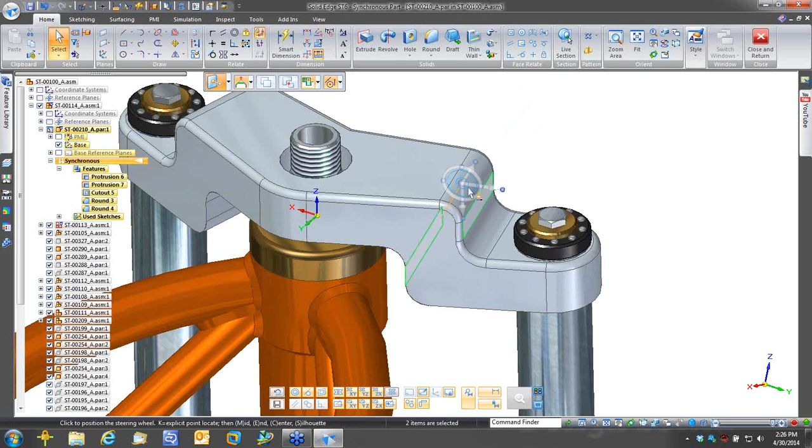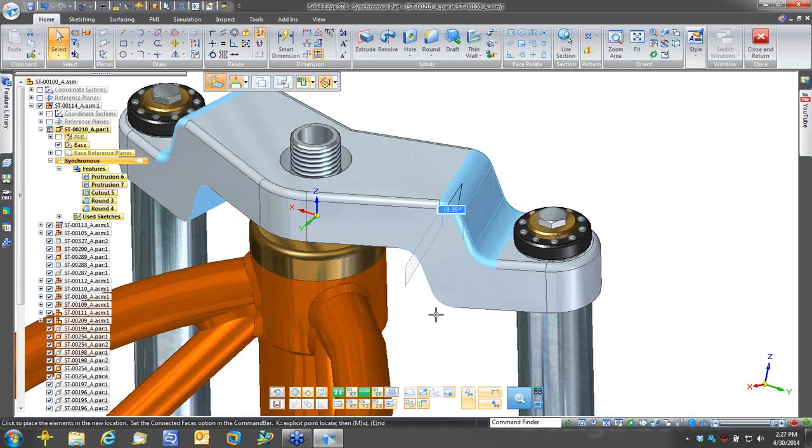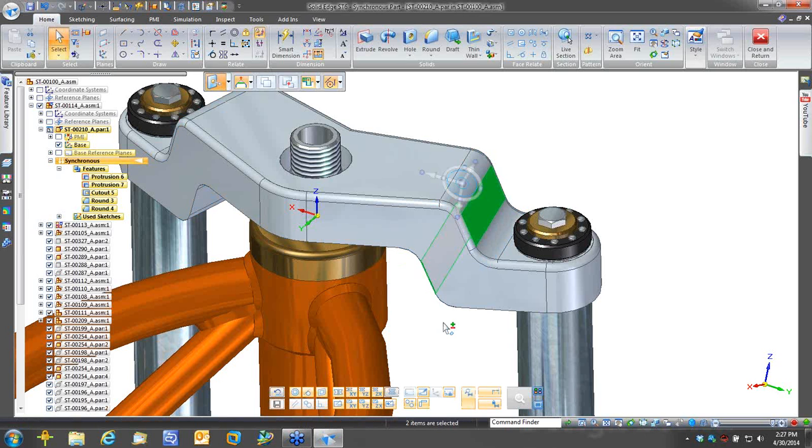The steering wheel allows me to snap to different elements of my part, and in this example, I want to take the torus of my steering wheel and simply rotate those faces some value. And in my case, maybe I want to put 20 degrees of taper to those faces, and make this part a little bit stronger, make it look a little more aesthetically pleasing to the eye.